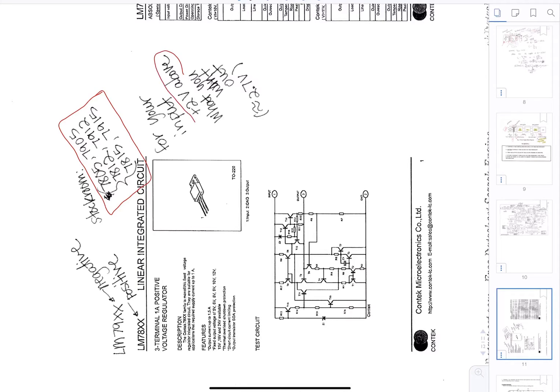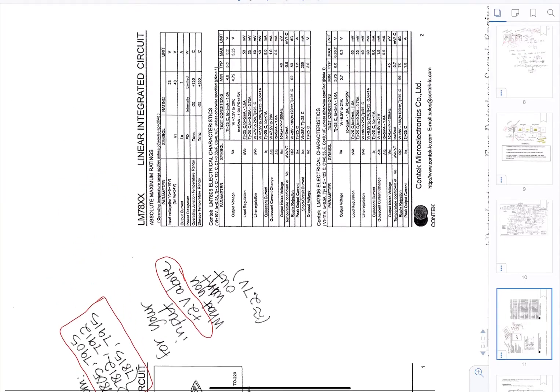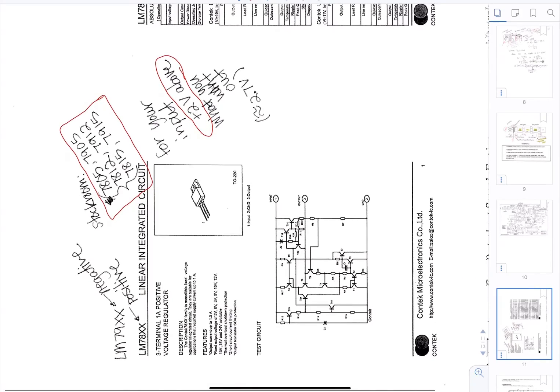And then again, just put 2 volts above what you want out, because it will drop it down by 2 volts. So if you expect 10 volts out, it will actually give you 8 volts out. So you want to be careful that you choose the right number.